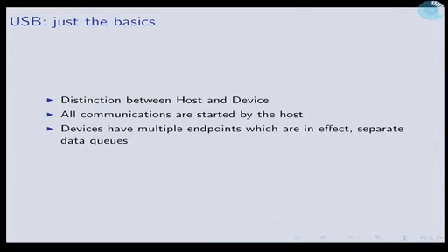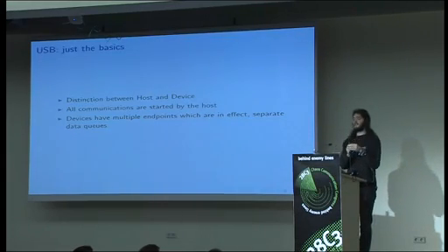So USB. It's worth noting that the host and the device are separate concepts, and that the host is in charge of all communications. If the device wants to say something, it has to wait for the host to ask. You can tell which end of your cable is the host and which is the device because this end plugs into the host, and the one that's more blocky plugs into the device.